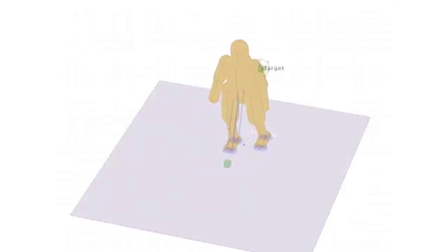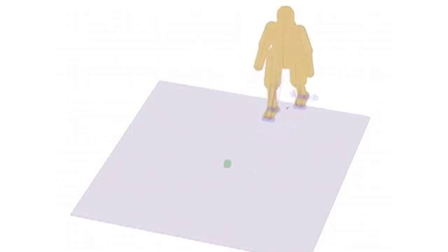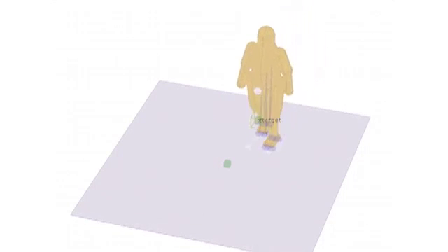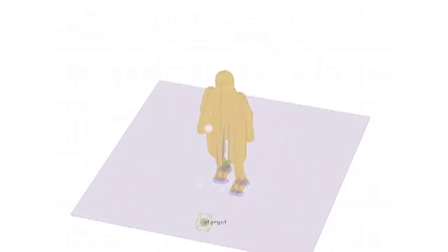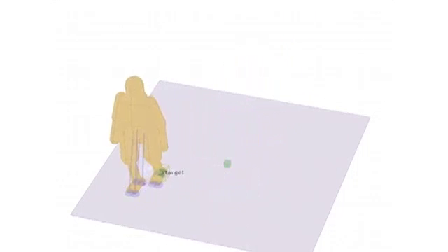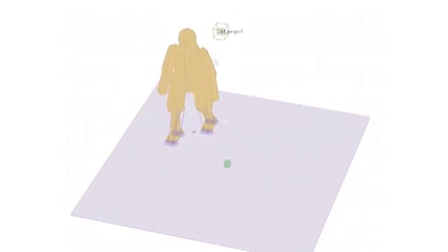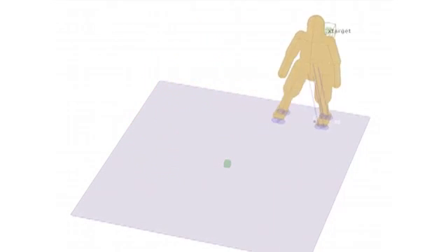And we can get very different behavior strategies coming out without doing any manual changes. We can control not just, say, the location, but also the heading, and that is incorporated as an input into the network. And again, using exactly the same network and architecture, we can set up a humanoid that is able to contact with the ground and has access to those ground reaction forces, which is how it actually ends up locomoting.